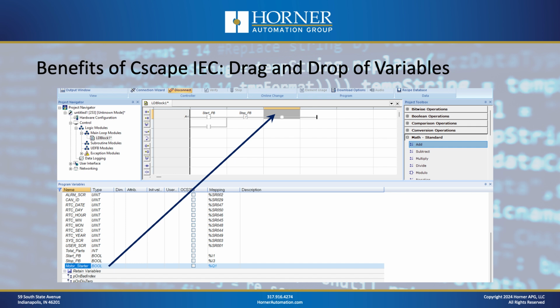Well, dragging and dropping of variables is what is common in most modern PLC programming packages. It's the generic IEC packages that just have the drop-down list or smart list. And you don't lose that in your IEC. You can drag and drop variables. You can also double-click on the function, the contact, the coil, the operand, and also have a smart list appear to choose your variable that way. So you have both. That's perfect.